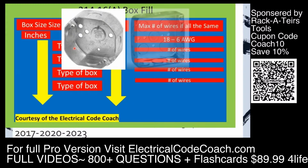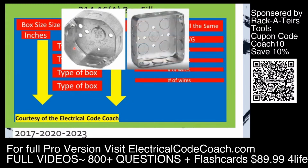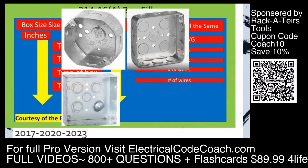The next 3 lines you'll notice say square. These boxes are true 4-square boxes. They're 4 by 4 by whatever the depth is. And if you look back over here to your dimensions where the box size in inches is listed, this box states that it's a 4 by 4 by whatever the depth is. There are 3 different depths. The next 3 lines you'll notice say square as well, but its dimensions are a little bit different. It says 4 11/16 by 4 11/16 by whatever the depth is.